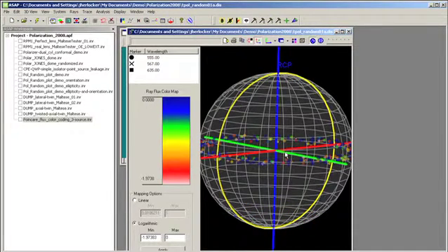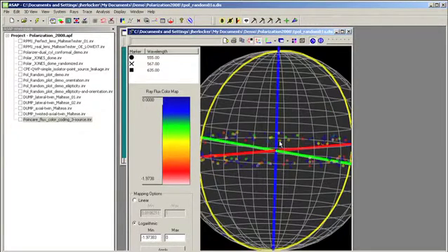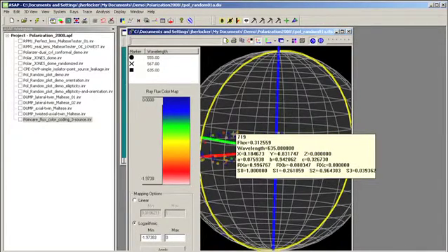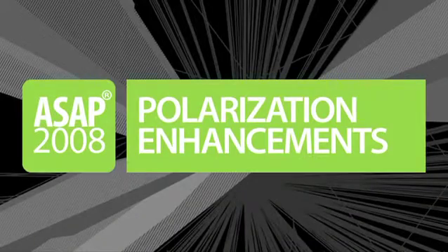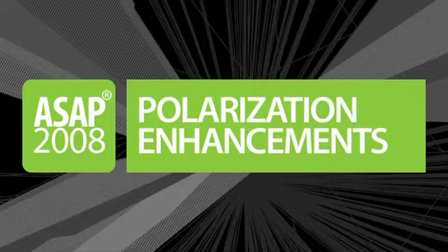see fine variations. By pointing to a ray data marker, a detailed set of numerical data are shown in a pop-up box, including index number in the dump file, flux, wavelength, position, direction, and polarization state. These data can also be sent to the output window. Together, these enhancements represent the next level in polarization ray tracing capabilities available to optical engineers and designers.